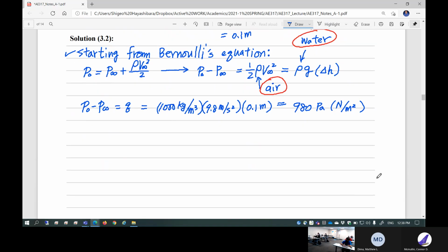Dynamic pressure can be determined by a pitot-static probe combined with, in this case, a U-tube manometer. Now, obviously, an airplane is not going to use a U-tube manometer to measure this kind of thing. It is usually associated with a digital pressure difference transducer or something like that. But this is the basic mechanism. So now, based on this dynamic pressure information, you are going to plug into the airspeed equation.